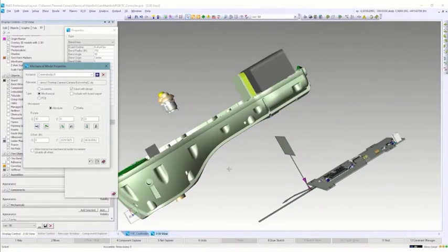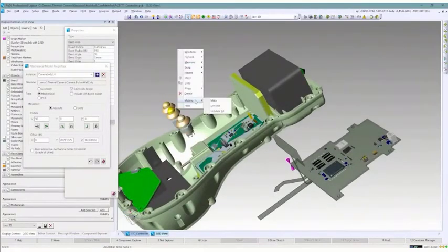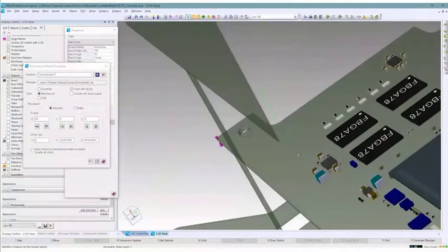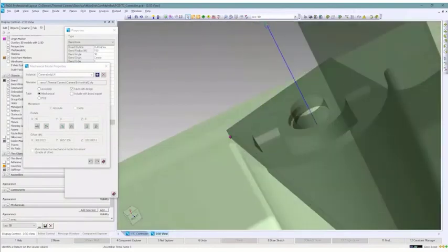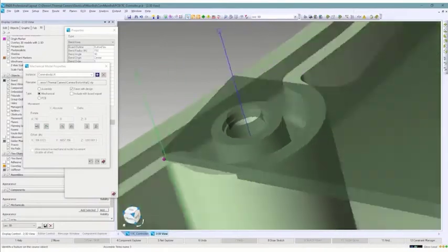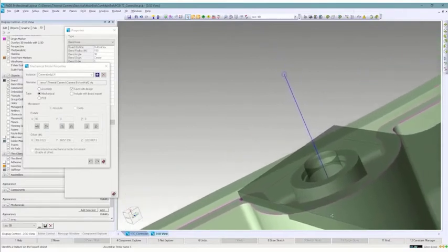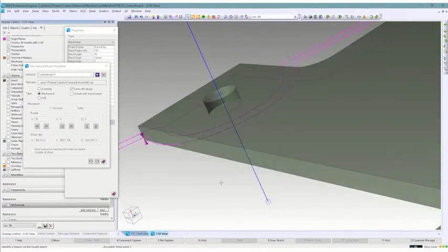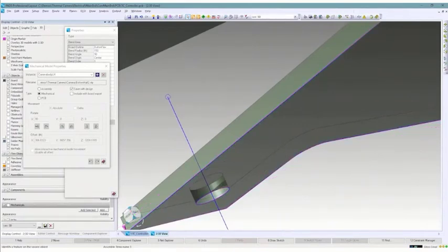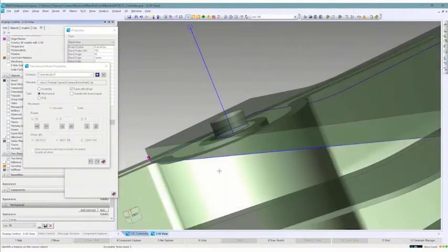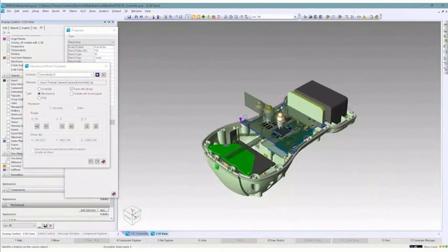But I can use mating capabilities in PADS Professional to actually mate it to the surface and axis, so I don't have to sit here and try and position it by hand. So we do right-click, mate, and then I want to mate by axis. I'm going to choose that location right there, come down to the board, and choose that location. All right. And that will line it up for us. And it may have already picked the surface, actually. Nope. So now I need to mate the bottom edge of the board with the top edge of the board. So we'll do align face. So I want that face there. And then to easily pick the bottom one, I actually need to turn the mechanical model off real quick. And then pick that face there. All right. Now that should have moved it into position for us. Yep, so it's fully mated with the mechanical model with a couple clicks, just like you would in a mechanical engineering tool.